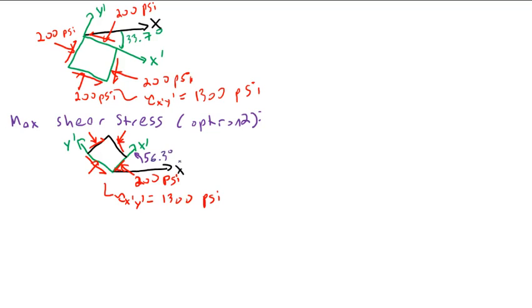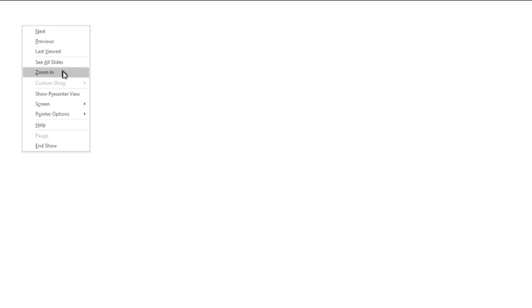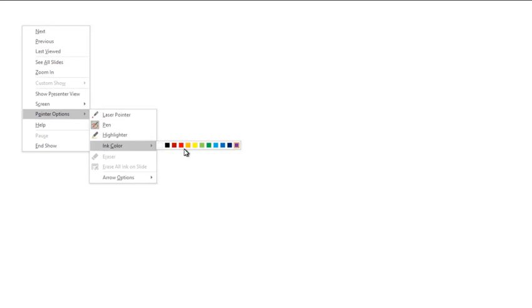Okay, so we've completed part one, finding the state of stress at that point. Now, what if I have the equations of Mohr's circle, but I wish to find the state of stress at a different point, or at a different angle? You got that? Okay, good. So we completed part A, which was to find the principal normal stresses, the max shear stresses, and the critical angles.